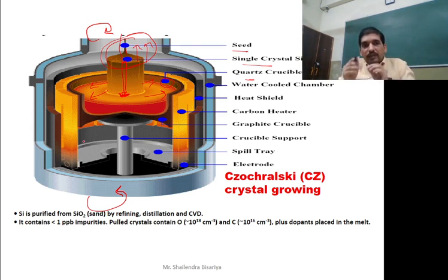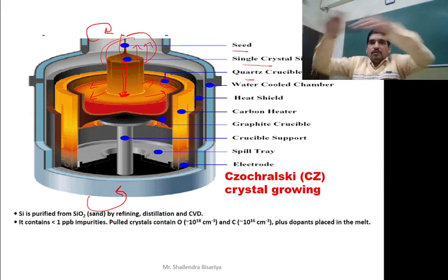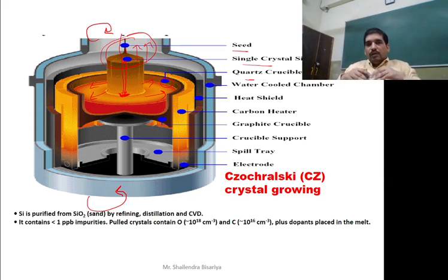That is how basically we get 99.9999% pure. If any impurity is still there inside the furnace in the molten state material, because of this force which appears due to the movement in opposite directions, it will pull the material from the center of the furnace towards the corners of the furnace. And when you are moving it, it is getting circular shape, single crystal shape, and you are pulling it out. At that time, the single crystal structure ingot will come out, and impurities will be moved away.